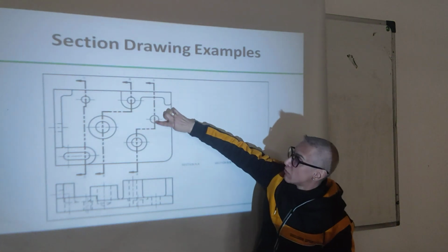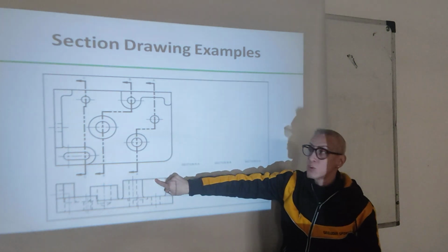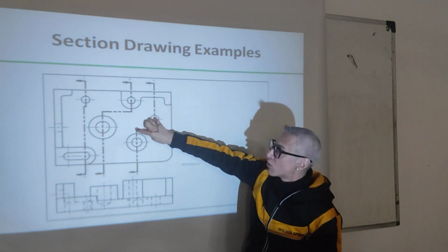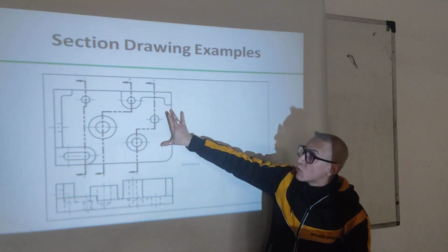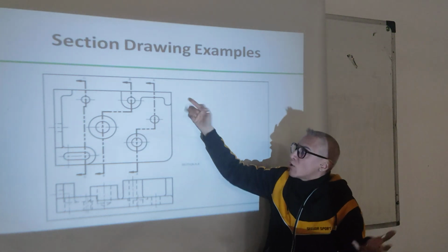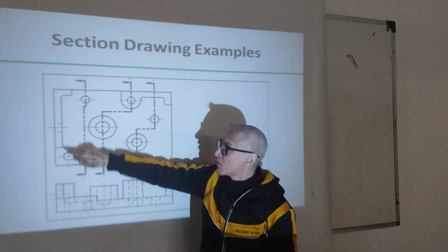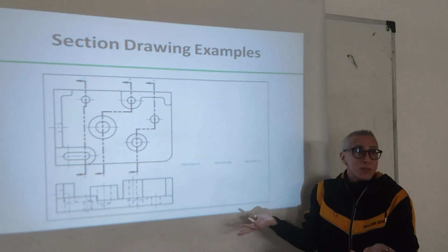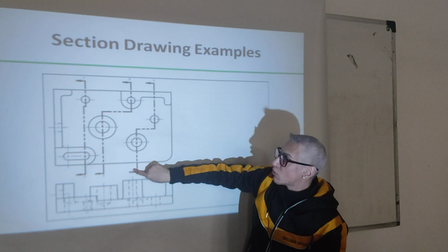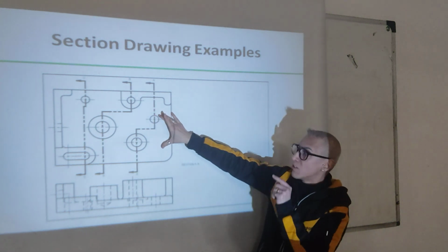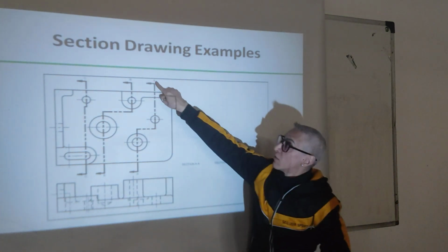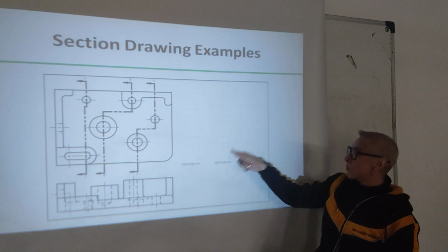Because the line doesn't go straight down, it's not full. It's also not half. It is a line going through this object, going this way, going through this object. It is with the intention to show these circles in one drawing. We cannot show this circle and this and this and this, everything in one drawing. It's not possible. So 3 offset section views have been chosen. But at least you save yourself 2 drawings here. 2 in 1, okay? And then 2 in 1, 2 in 1. So 3 offset views, marked section AA, then section BB, and section CC.